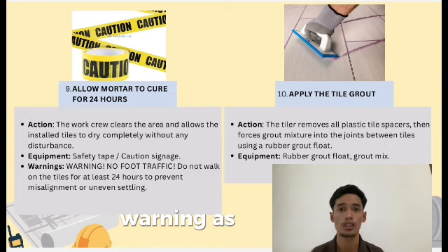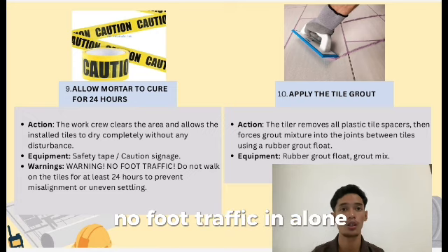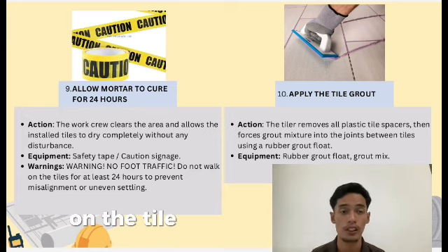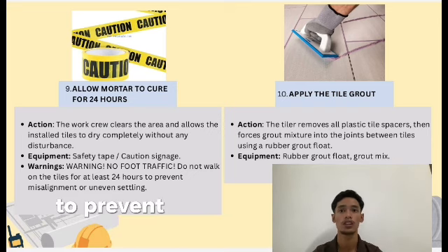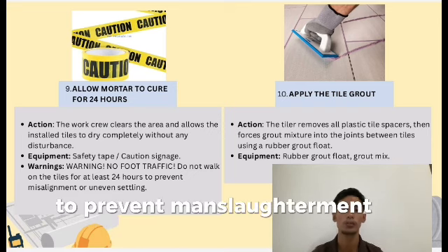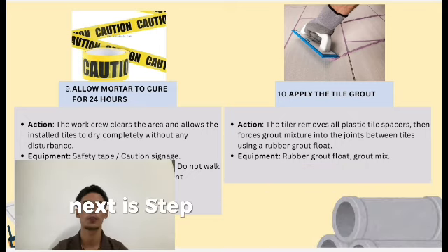Warning: no foot traffic is allowed on the tile for at least 24 hours to prevent misalignment or unsafe settling.